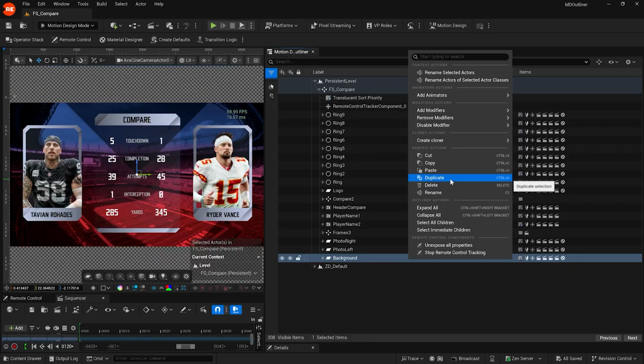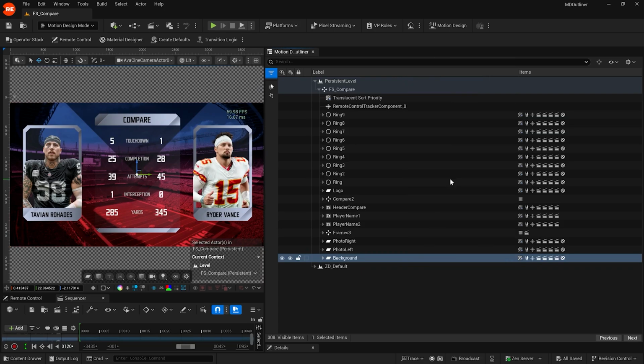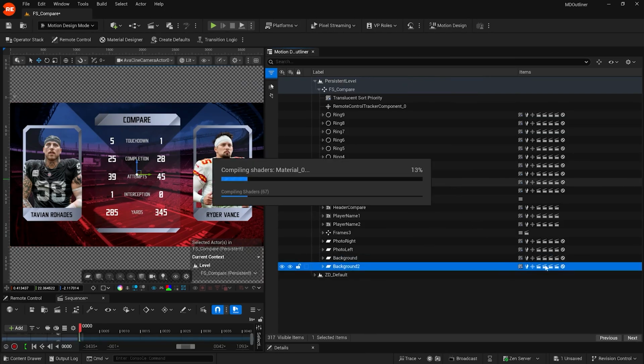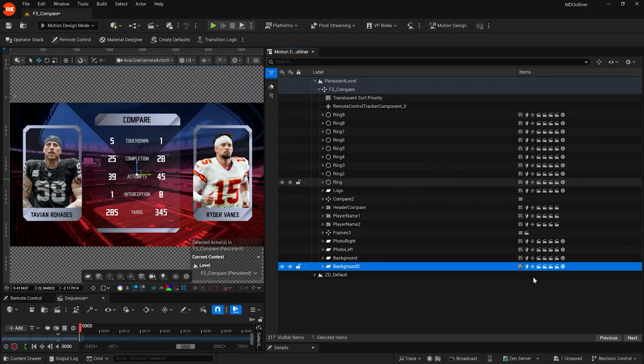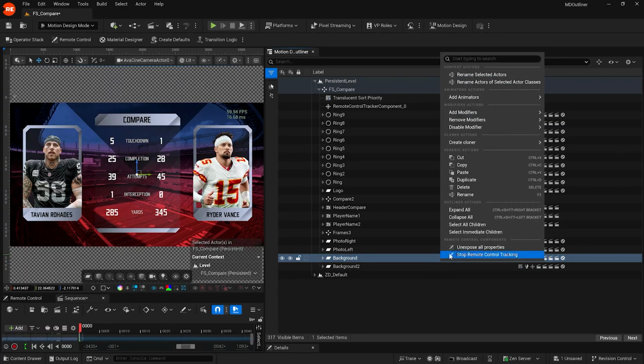However, in motion design specifically, duplicate does not only copy the object, but also all its items. So if you copy an object linked to animation, you will also be copying its animations, and the sequence will include this copy animation of the copied object. Or if it uses a modifier, those modifiers will also be copied. In addition to your generic actions, you can also access shortcuts and actions from other panels here.